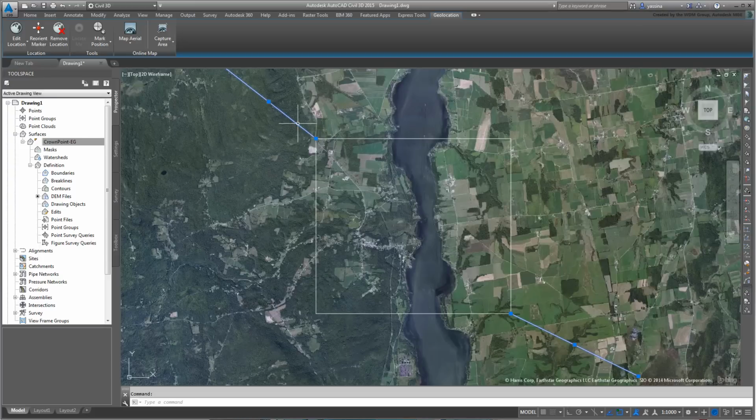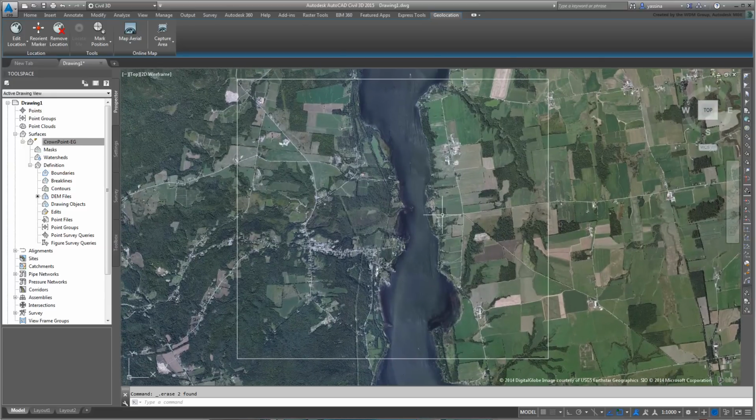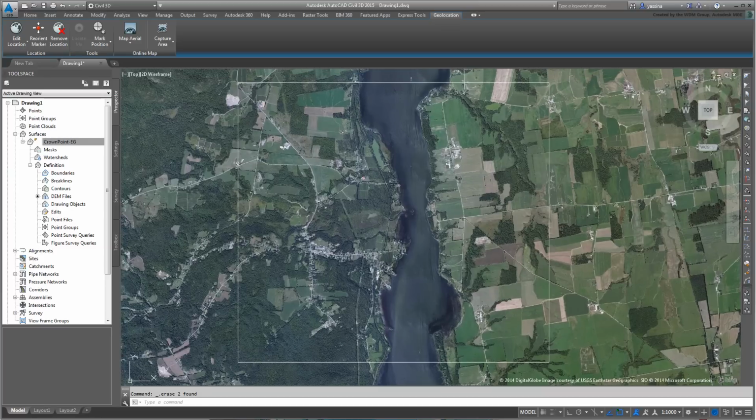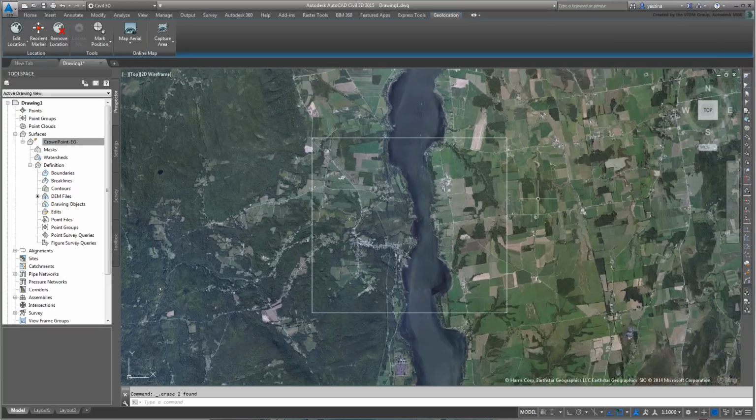The area inside the rectangle is the area of interest. Both the surface copy and the Civil 3D aerial maps will be restricted inside that rectangle. It is also the same size as the texture image you created earlier. This ensures mapping coordinates work well when the map is later projected onto the terrain in 3ds Max. To crop the Civil 3D background map is very easy. Simply use the Capture Area tool and snap to your rectangle.